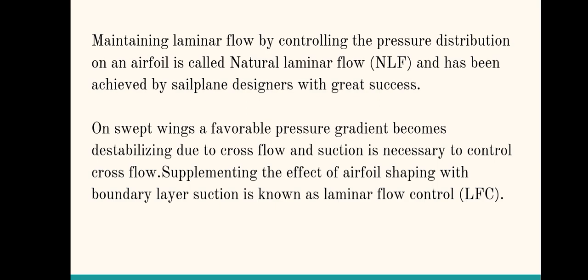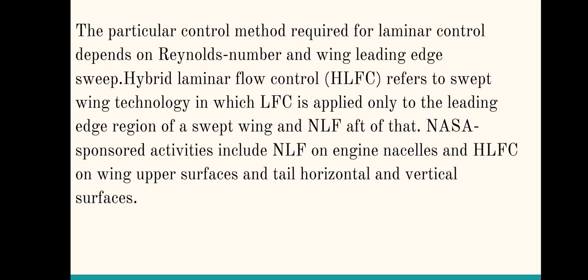On swept wings, a favorable pressure gradient becomes destabilizing due to cross flow, and suction is necessary to control cross flow. Supplementing the effect of airfoil shaping with boundary layer suction is known as laminar flow control, that is LFC. The particular control method required for laminar control depends on Reynolds number and wing leading edge sweep.